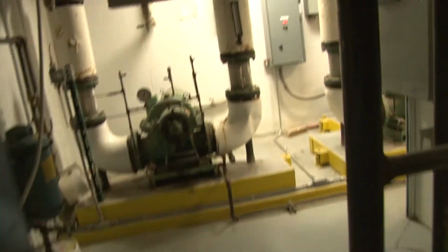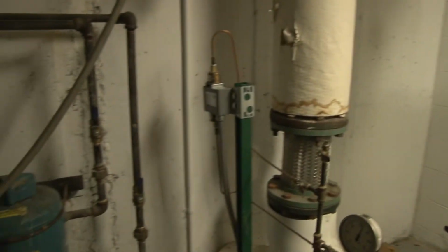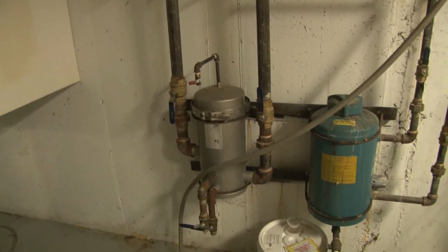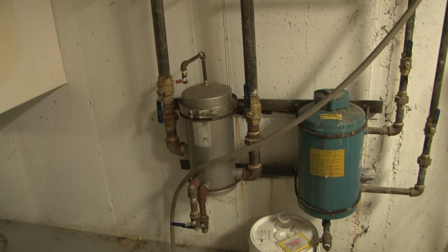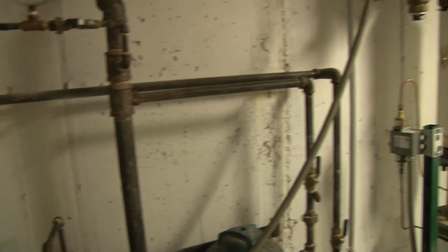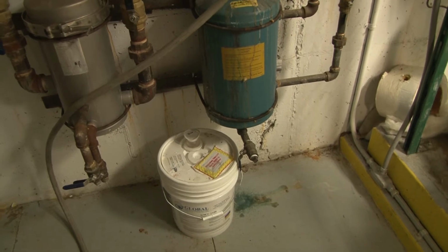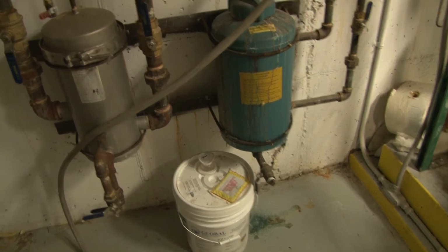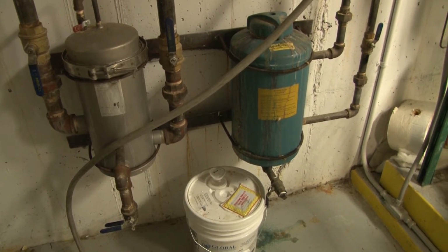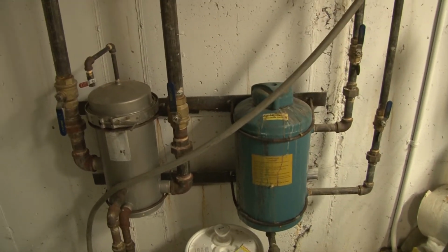Let's go in the back to see the back of the room. We can see our pumps. We also have our chemical feeder and the filters to remove any impurities from the closed loop. We can see our gauge that tells us the pressure of the water circulating, and we also have a bucket of chemical. It means that a technician did some water testing and found that the oxygen levels in the closed loop were too high, and an oxygen scavenger was injected into the system to absorb the oxygen and prevent corrosion